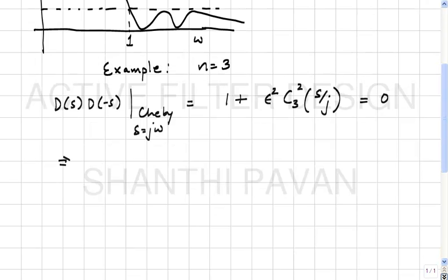So all that we need to do is find the polynomial for the Chebyshev, and then do this simple flip. And how do we find the polynomial for the Chebyshev denominator? We know the roots, the poles in the left half plane, from which you can find the polynomial.